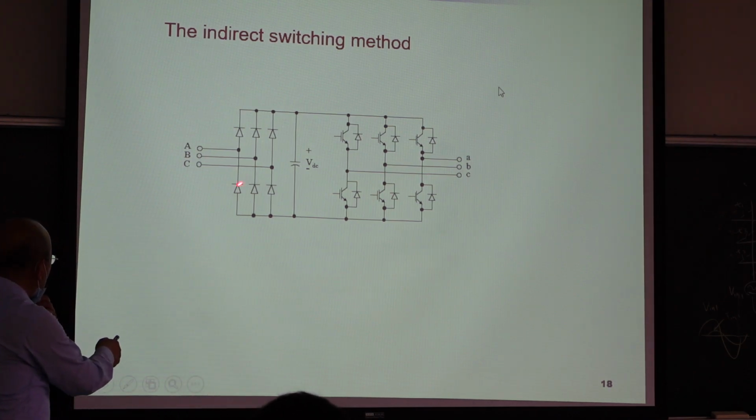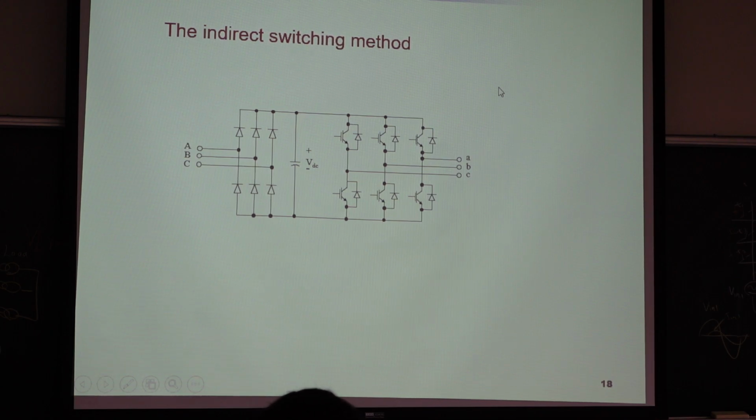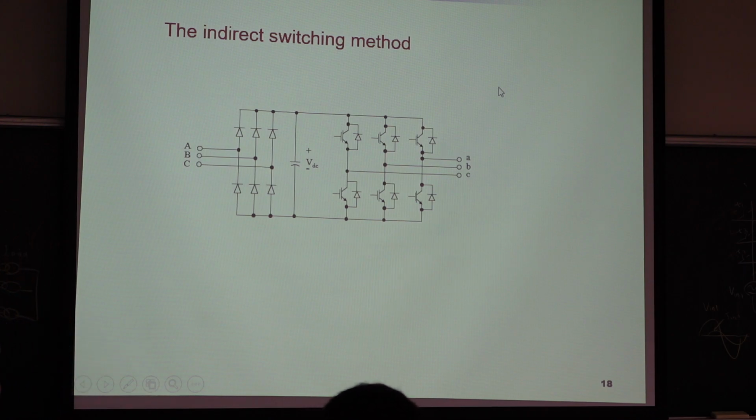How about the power factor? Which one has the better power factor? Here, what is your voltage? Your voltage is here. How about your current? Your current is here. Do you think that the power factor is good? Not good. You need a PFC. How about this one? You have switching 1, switching 2, then unity power factor.